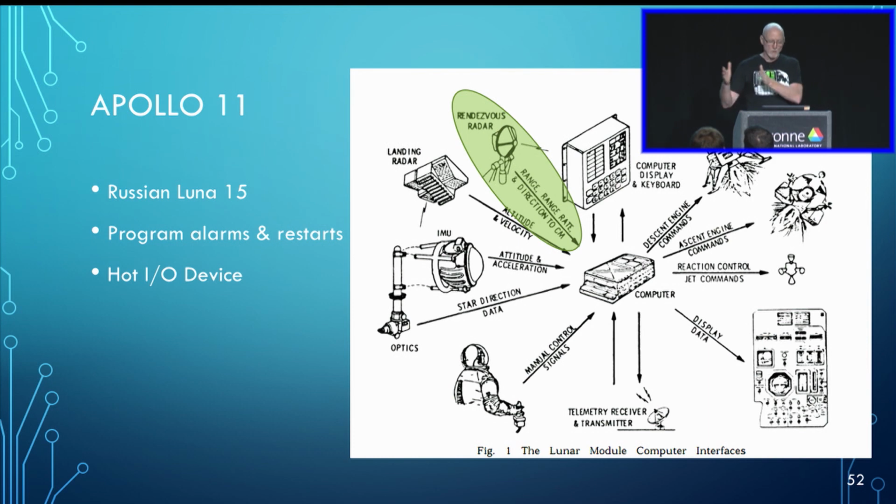Because of that, the computer was not making the progress through its scheduled guidance activities that it needed to, that it expected to. And so when it read new job, at some point it realized, oh, I can't start a new job, restart. And this happened 4 times. If you read a lot of the mainstream media, they'll claim, well, the computer malfunctioned, or Armstrong basically had to take over manual control.